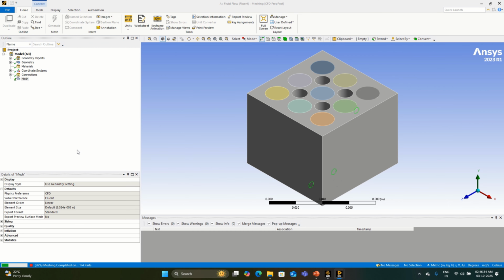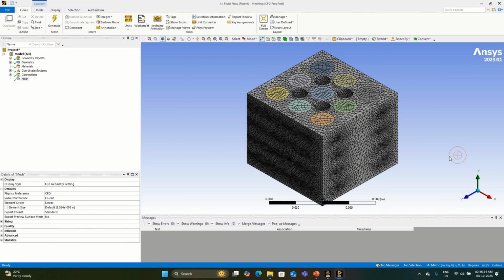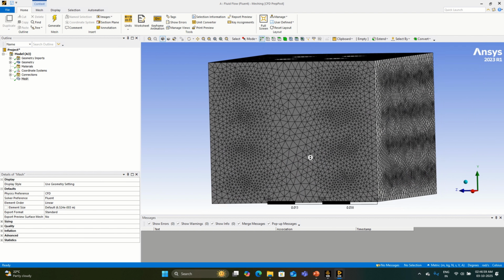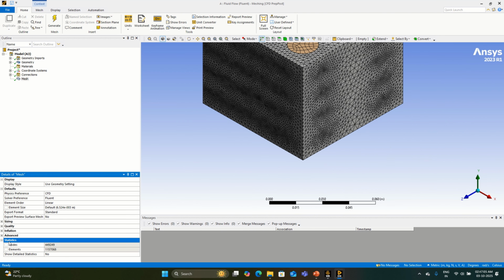This will be the default mesh that is going to be generated, but default may not work as it may not have sufficient number of nodes and elements which are been properly distributed. So we might have to modify the geometry. So accordingly we'll check out what can be done. So you can see this is how the mesh is been generated as of now. Let's see the count. So we'll just take it 0.005 first, or 0.001, and let's make it generate.